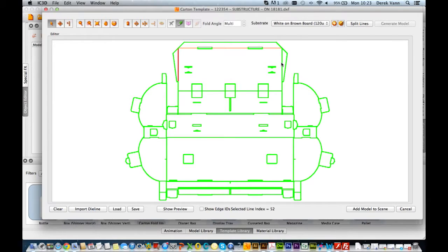However, by holding down the Shift key and selecting them, you can then change them both to individual folds with the toolbar Folds button shown red. The next set of horizontal lines are collinear, and holding down the Shift key, these can be selected then linked as folds again using the Linked Folds button in the toolbar shown orange.